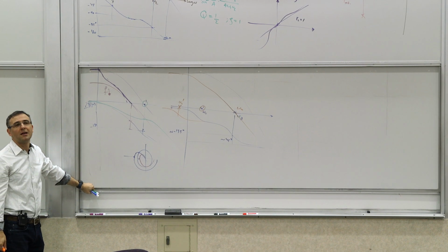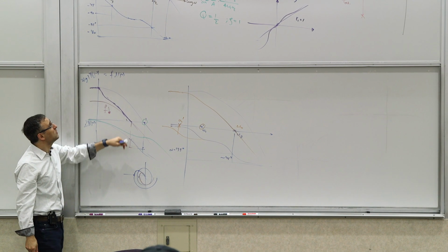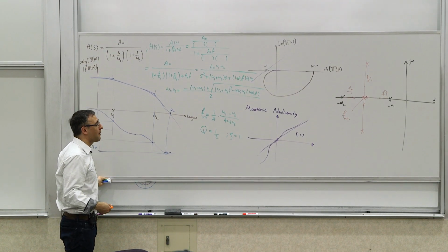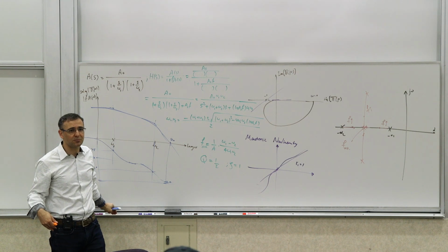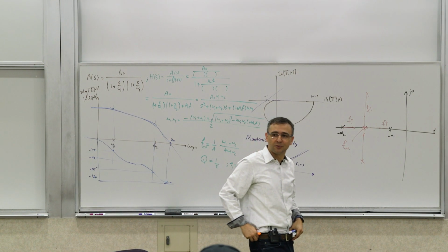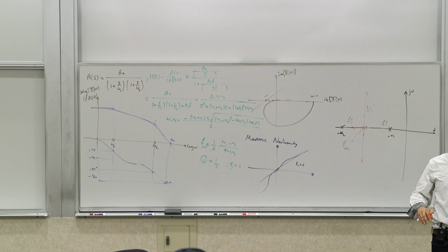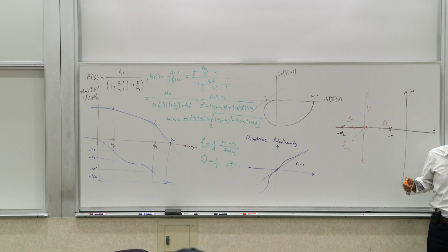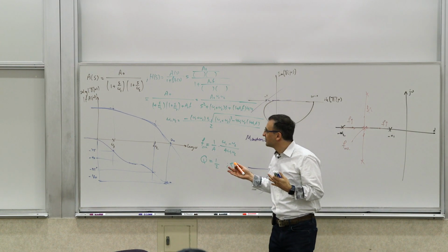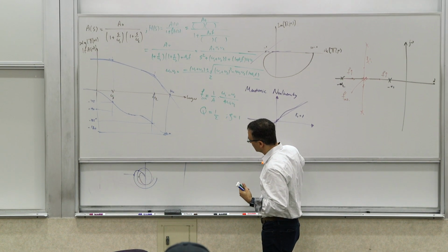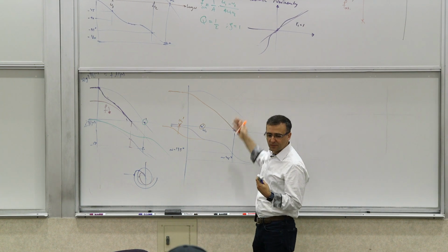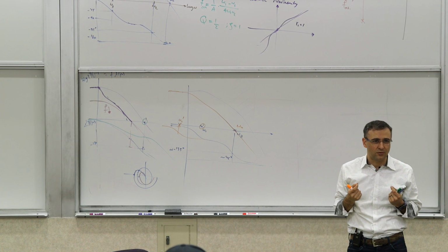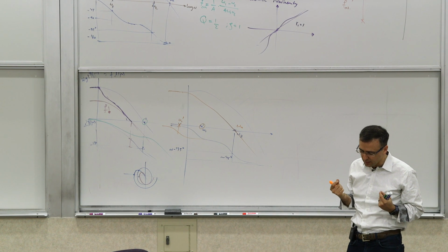That's why we are trying to avoid it, though it's not a hard and fast rule. There are people who make op amps, and I have made op amps, with 3 stages of gain, but you need to really be careful about how you do that. So it's not that it absolutely cannot be done, but if you're doing something vanilla, you need to be careful about that stuff. So you want to minimize the number of gain stages if you can. That's the first thing that you want to think about.